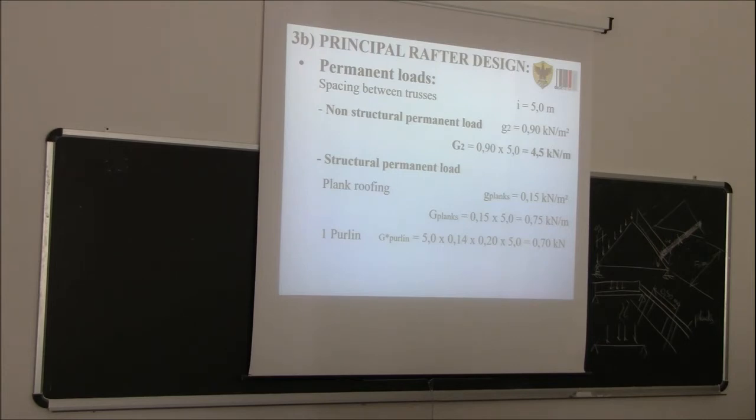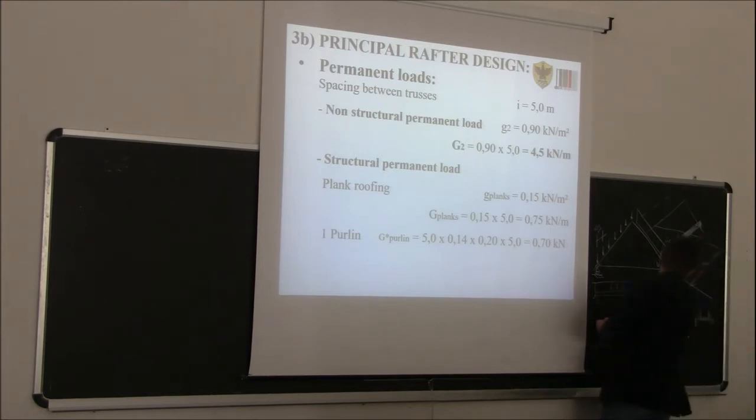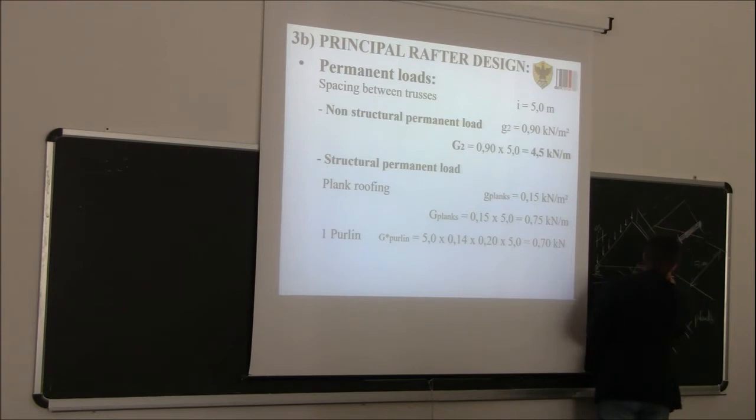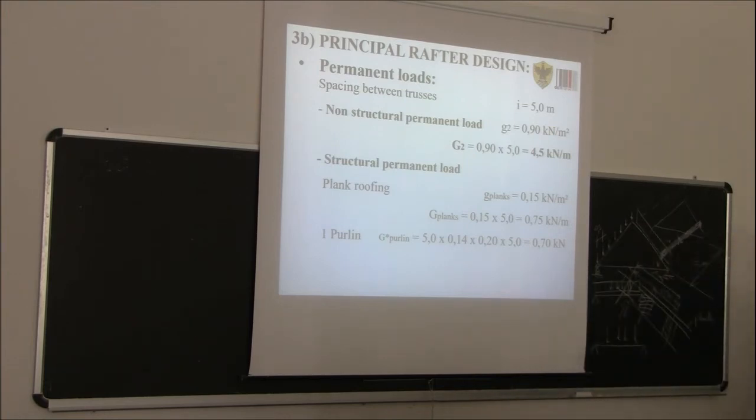Okay, I have told you that. So, another one here, another one. So you say 1 meter, this is 1 meter, right? So I count 1 plus half plus half. So basically 2 purlins per meter, okay? So meaning that if I now want to calculate the weight, the equivalent uniformly distributed load per meter, you just double up this value here.